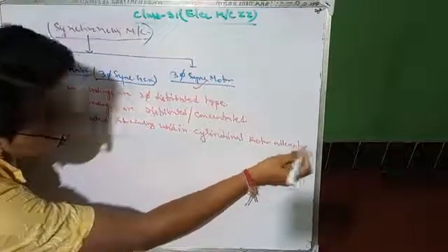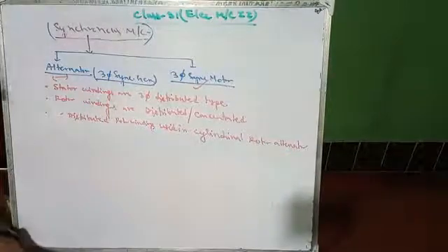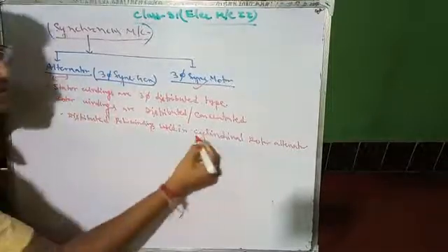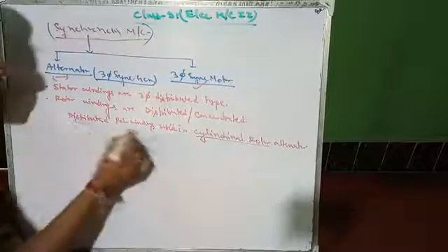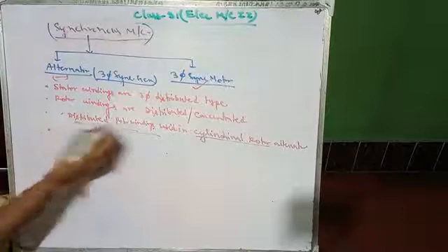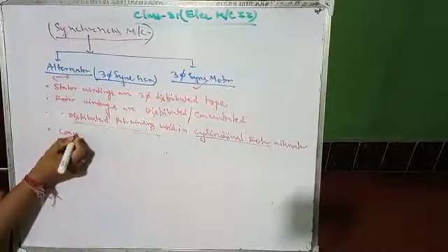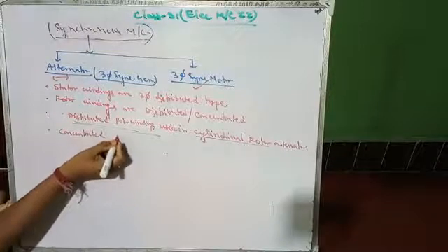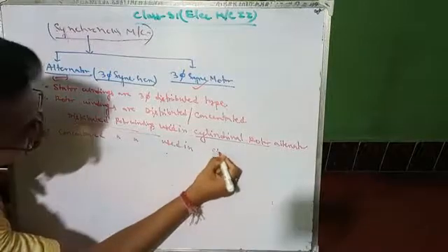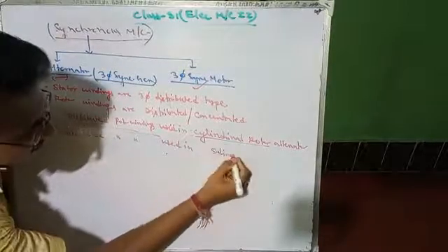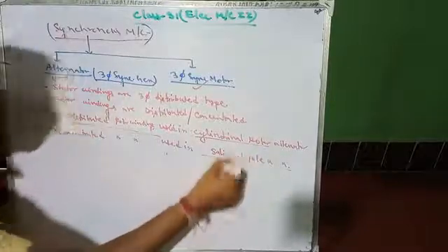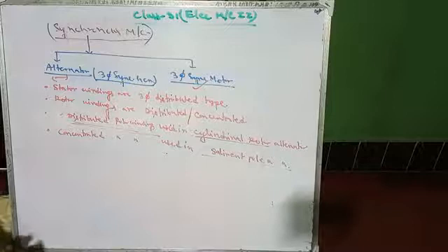There are two types of rotor used in an alternator. The first is the cylindrical rotor, where distributed rotor windings are generally installed. For concentrated rotor winding, it is used in the salient pole rotor alternator, S-A-L-I-E-N-T, which is the second type of rotor used in an alternator.